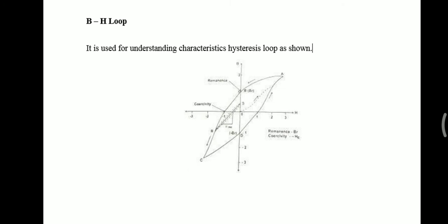The operating point depends on the shape of the magnet and the permeance of the surrounding magnetic circuit. If the magnet is surrounded by a high permeability magnetic circuit, its poles are effectively shorted together so that H is equal to 0, and the flux density is the value called remanence.